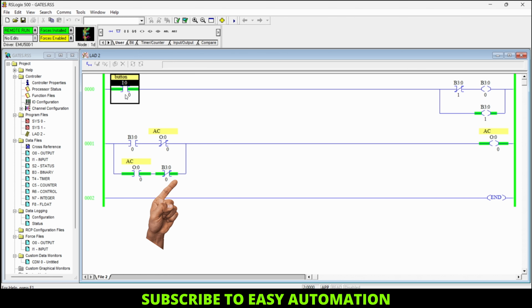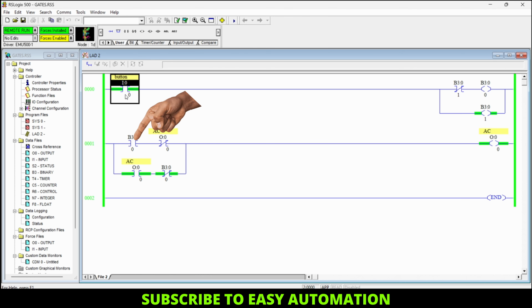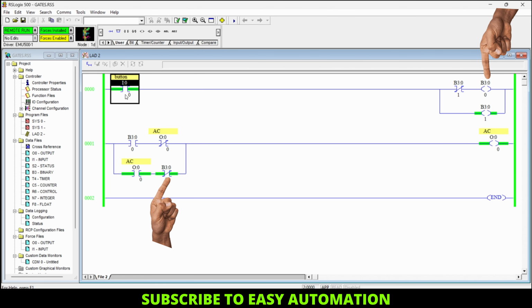And I think you have got a question: we are going to give a trigger pulse to this NC contact as well, so why won't this NC contact break the supply for our output coil? As I said before, the program is compiled from upper side to lower side. So whenever I give the trigger pulse, it first comes to this NO contact, then the output will go high, and before the output goes off, this pulse has gone off. So this NC contact will become NO again, and our output will remain high.